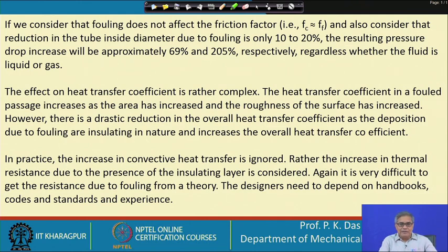This is a very important observation: we have to have a heat exchanger that is free from fouling as far as practicable, and if there is fouling, we have to take some strategy to mitigate it. Now, as we proceed, we will see that fouling is a continuous phenomenon. It is a transient phenomenon, but it takes place continuously.